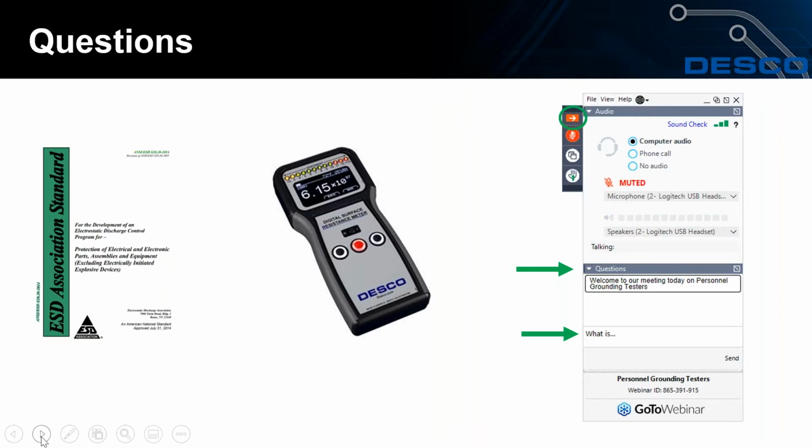Well, that's because as resistance steps up, I mean, we all understand resistance, I think, here, but as the resistance goes higher, it takes much more time for that test voltage to get through that resistance, if you will. And so because of that, we not only need to test longer, which is something I'm going to show you too, or apply that voltage for a longer period of time, but accuracy falls off. So keep that in mind, that if you are really big on extreme accuracy, you're going to see a drop off in that as the resistance of your materials gets higher.